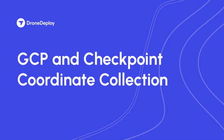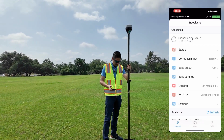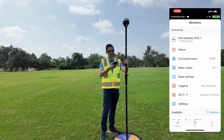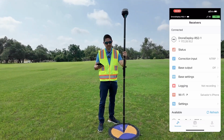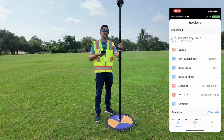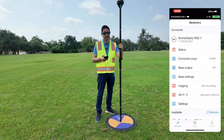All right, our first step on getting the site survey done with the ground control points and the checkpoints: we decided here to start on the edge of the site with a checkpoint. Now, a checkpoint is the exact same thing as a ground control point. It's still a point in the ground that you survey with your GNSS station. You're going to record the coordinates and upload them to DroneDeploy. There's nothing that changed practically in these points between the checkpoints and these ones. It's just that the checkpoints are not used for processing, but we do need them to actually evaluate the accuracy